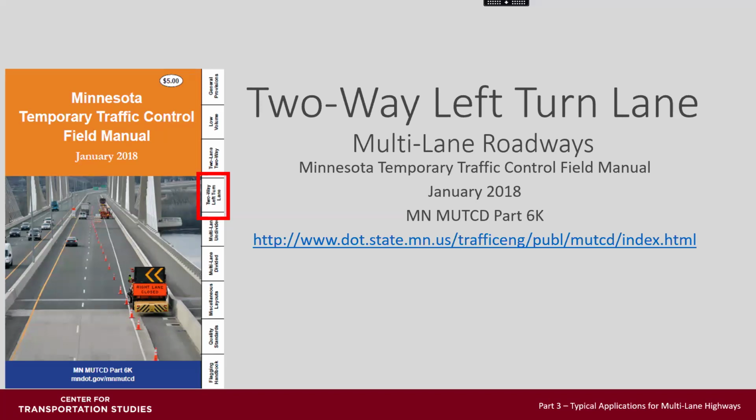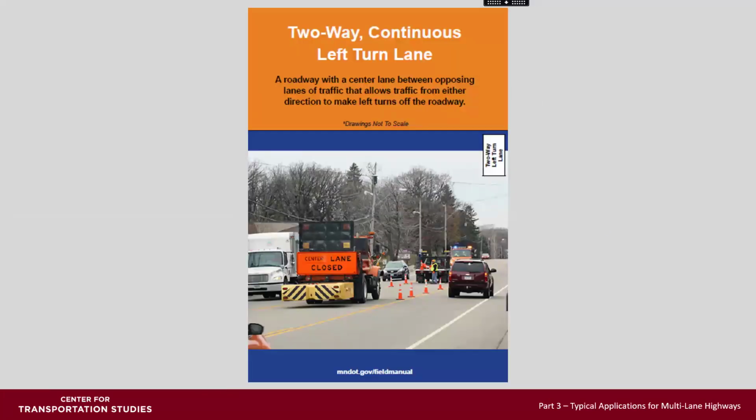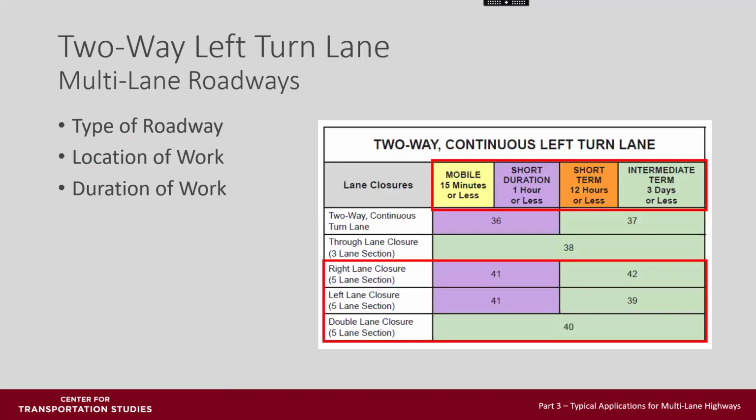Let's take a look at two-way continuous left turn lanes on multi-lane roadways. There are several layouts in there for 5-lane sections, having right lane or left lane closure or a double lane closure, and showing the different durations of work.